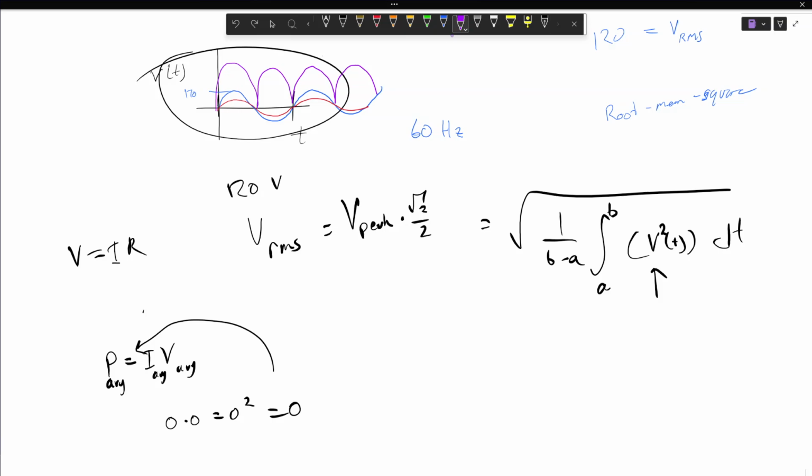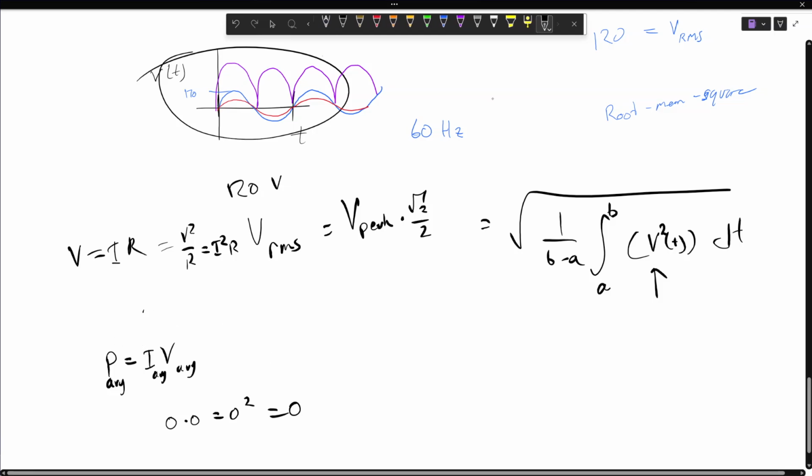And so we invented this math because at some level, when you take a function times a function, that's where if you look at either V squared over R or I squared times R, you're taking that function squared. And that's where when you take this average to renormalize it, you square root it, but you take the square thing to go from any individual piece to the power. That's sort of the utility of this so-called RMS value.